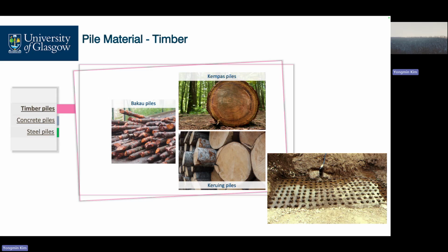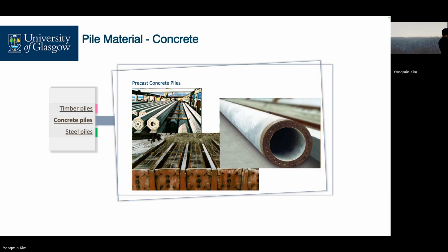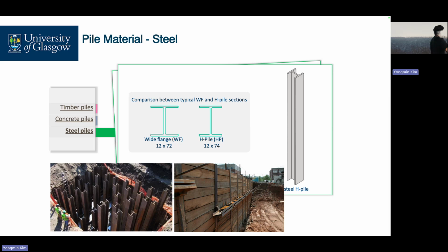Timber is very old, outdated. Concrete comes in different grades with different bearing capacity. Even for higher buildings, we should go with higher concrete strength. This is the compressive strength, right? 40 megapascal. And sometimes we have circular concrete pipes and different shapes, prefabricated RC pipes.